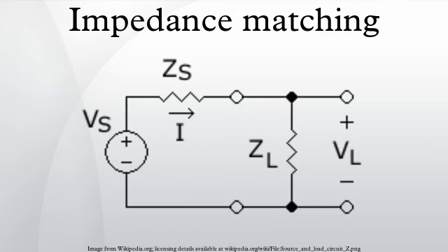On the power grid, the overall load is usually inductive. Consequently, power factor correction is most commonly achieved with banks of capacitors. It is only necessary for correction to be achieved at one single frequency, the frequency of the supply. Complex networks are only required when a band of frequencies must be matched, and this is the reason why simple capacitors are all that is usually required for power factor correction.